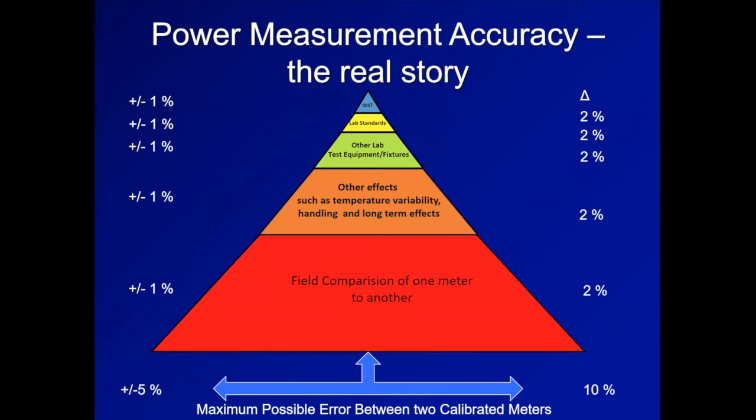Now, we don't use calorimetry because calorimetry is typically used under power. So we use a second type of standard, which is basically a calibrated reference generator. It's basically a signal generator, but it is a very highly accurate signal generator in terms of its guaranteed output. And that's what we use as a standard. Now, as I said earlier, these are secondary standards.